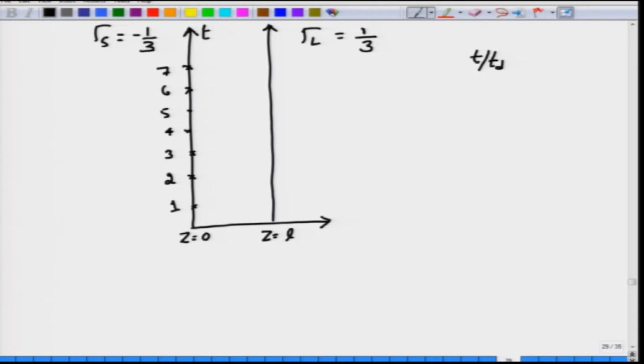So, you start out with Z equal to 0, at which point you are going to launch a voltage which is V1 plus, which is 30 volt, on the transmission line. We have drawn a line here because the delay will be essentially linear, and the load will see the incoming or incident voltage of 30 volts after exactly one time delay.